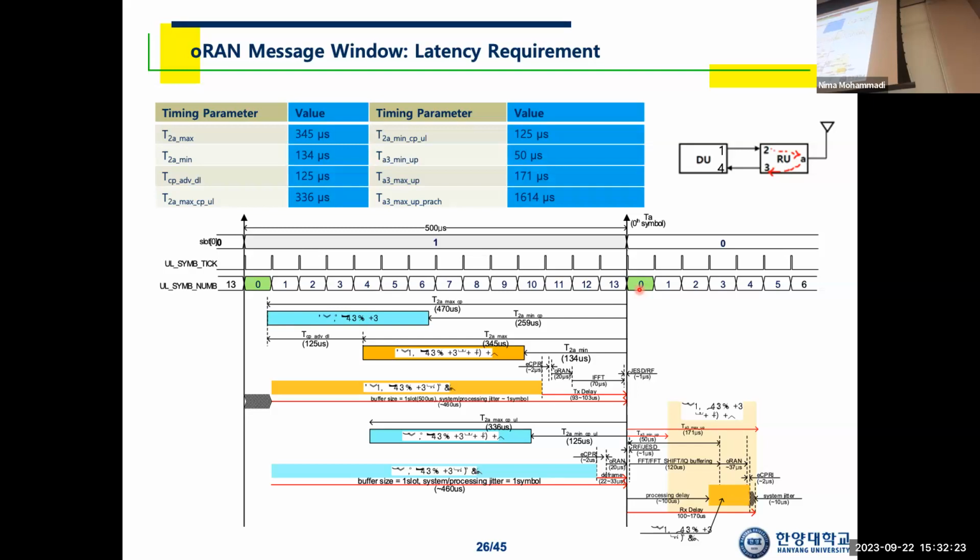forward Fourier transform and framing procedure. You have to map these complex values, which are the result of the forward Fourier transform, into a packet. You have to change these OFDM sample values into the corresponding packet. Okay? So you have to pack up all the OFDM sample values to be loaded on the packet, and you complete making the physical layer packet by this moment.